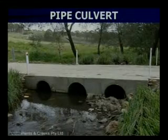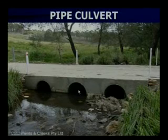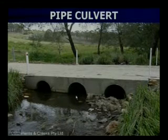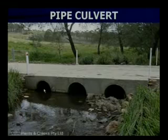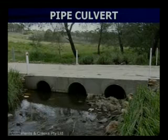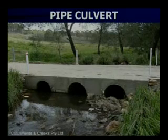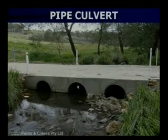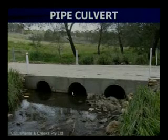So shall I show you a pipe culvert? Yes, here it is. Herein you can see in the picture a pipe culvert. You can see the road here. There are 3 pipes here which are basically provided to carry the water from one side of the road to the other side. Based upon the volume of water to be handled, we can have a number of pipes. Sometimes we have a single pipe, 2 pipes, 3 or even 4. This is the road. In order to provide uninterrupted traffic, this is one method of providing a culvert. The purpose of this culvert is to facilitate safe transportation of water from one side to the other.